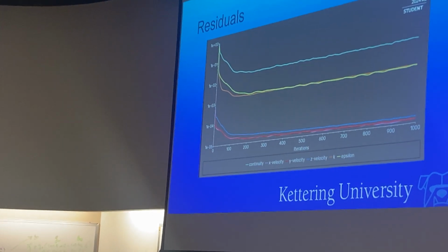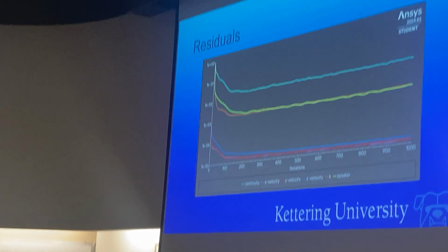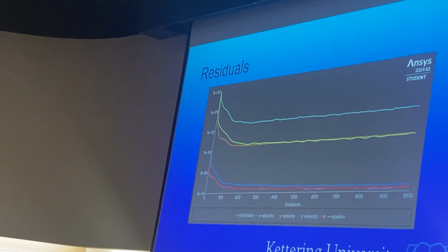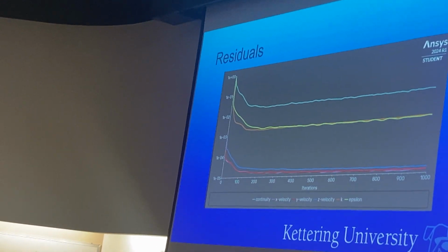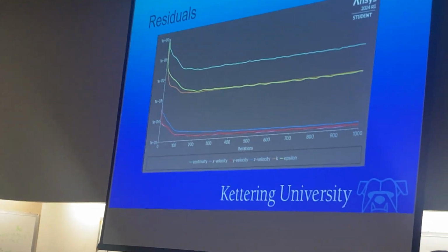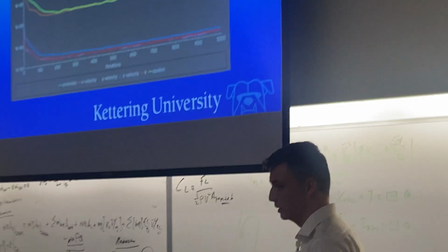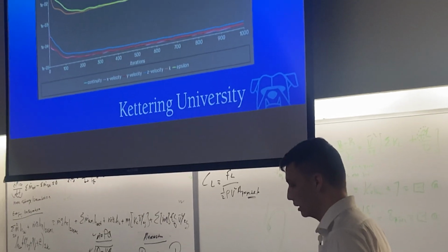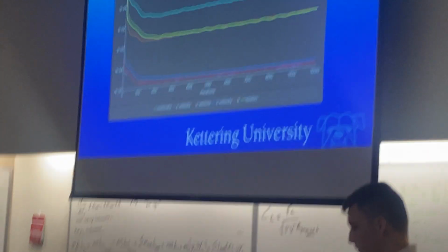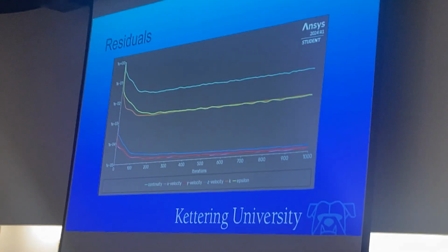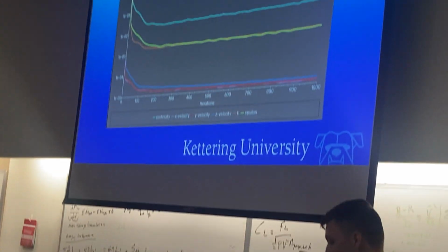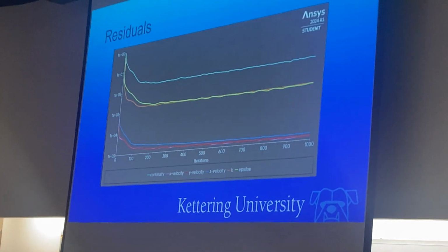This is more of a simple model, so it can easily get longer than that. But as you can see, after about 200 iterations, it basically reached the values we want to see, and it converged to decently acceptable values, considering we have to make 10, 20 more simulations. So from here on out, we stuck with 200 iterations.